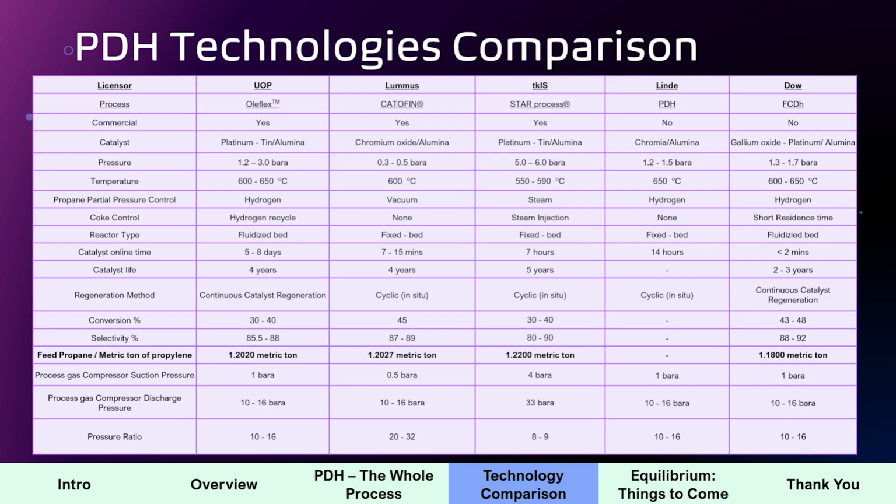It's a highly deep vacuum, so you can imagine the operating cost associated with having to maintain it and spend all this amount of steam on injectors. Now, ThyssenKrupp came up with another idea: let me focus on the partial pressure of propane, but still maintain the total pressure. So the total pressure is still going to be above atmospheric, but the partial pressure of propane is reduced by the presence of steam.